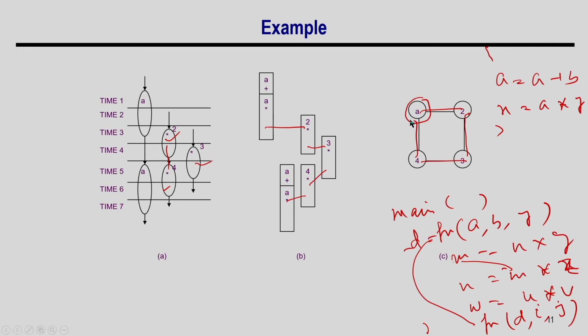So, this is my complete graph, but is this graph chordal? The answer is no, because there is no chord. I have a cycle of 4 nodes, but there is no chord. So this is not a chordal graph and hence not an interval graph. Then if I try to solve this problem, I cannot apply the left-edge algorithm.